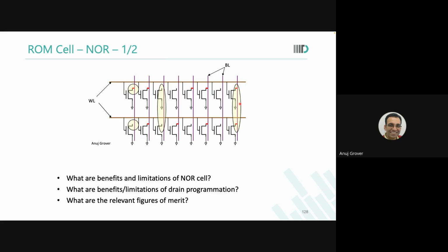Are you able to see this? So your memory cell is in saturation. It's like a current source. It is sinking some current. Now the duration for which this one is connected to whatever capacitance is going to determine what is the charge that you sunk. Whatever voltage this capacitance stored, is that important? No. You have a current source. It is in saturation region. You change the VDS, doesn't matter. Current will remain almost the same.